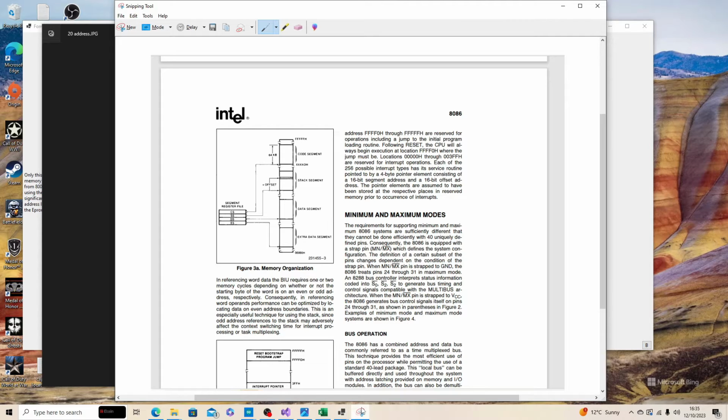You saw that to add the 2 EPROMs, I had to drop off the A0 connection and use the A15 address. This A15 address comes from the last bit of the first 4 bits of the 20 address lines. But as I'm only using 16 bits and so restricted to 64K, that's why I just connected this bit on the EPROM to +5, or 1. So for the EPROM, this top address bit of the 16 address lines will always be 1. I can do this only because I'm only ever using a 64K block for this coding exercise.